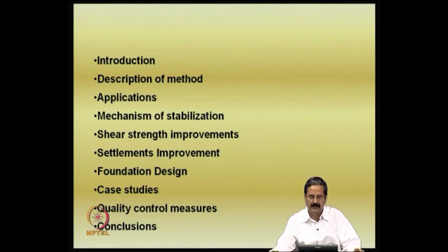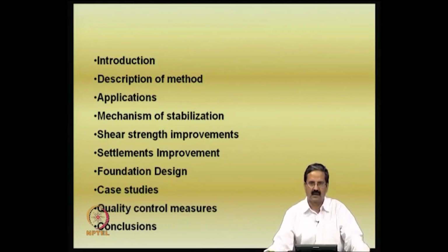So one should really be worried about how to handle this, and there should be a systematic way of understanding these techniques. Otherwise the technique may not be properly implemented in the field, and finally it leads to much more problems. For example, I must tell you the classical case of lime treatment itself. Lime treatment is very effective if there is no sulphate in the soil, but if sulphate is present in the same expansive soil, then it becomes worse.